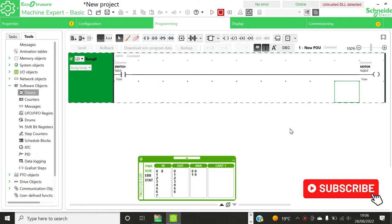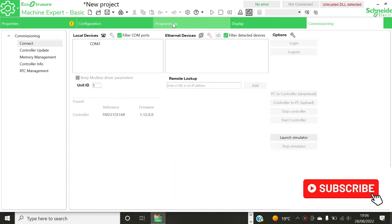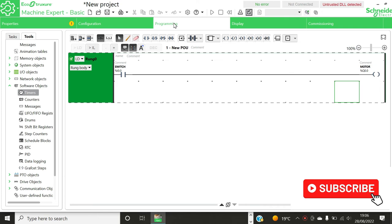We can add a timer to our diagram so that when we switch on, the motor does not come on immediately, but rather delays for a specified amount of time, and then it comes on. To achieve that, we'll need to use an on delay timer, but we first go to commissioning and stop the simulator so that we can add a new component to our program. We can then go back to our program.